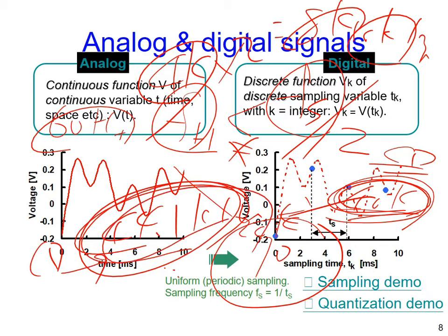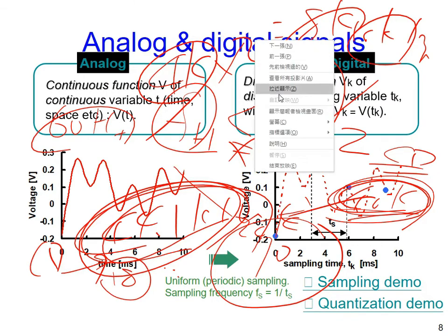How many bits? For high-end audios, I guess more than 20 bits will be best. In the past, maybe 18 bits. But right now, according to some kind of delta sigma data converter, it is pushed higher than 18. So at least 20 bits, even for your mobile phone. 20 bits means almost mission impossible for traditional ADC or DAC design. We need some kind of innovative structures for that.